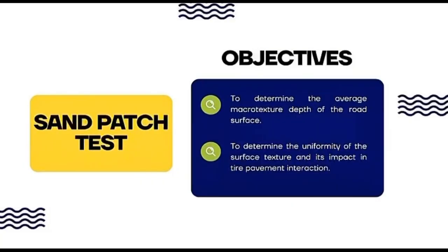Next is the sand patch test. This test will be conducted to determine the average microtexture depth of the road surface and to determine the uniformity of the surface texture and its impact on tire-pavement interaction.